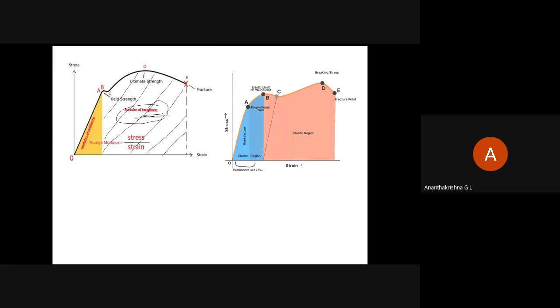If the material is very tough, that means its yielding is larger. Therefore, aluminum has better toughness than cast iron, because cast iron breaks with no yielding, so it is strong, but it is not tough. But aluminum is tough because it has more strain absorbing power. The area under the stress strain curve of aluminum is large, so its toughness is also more.